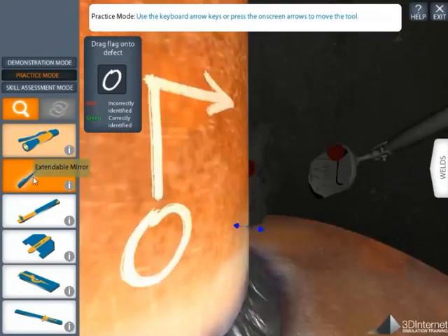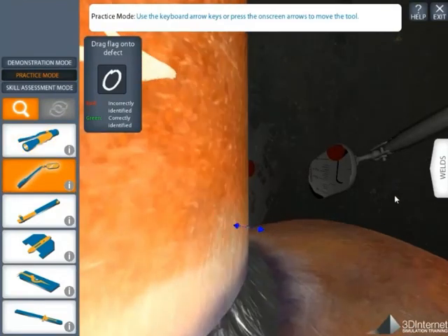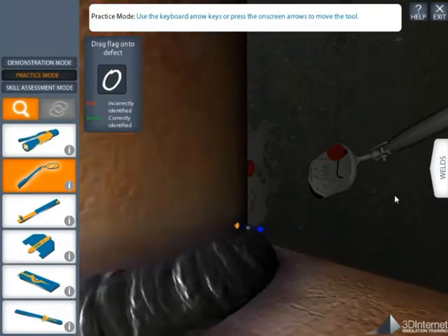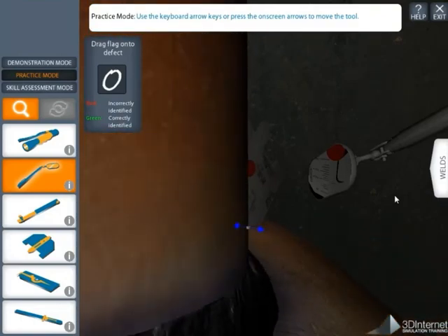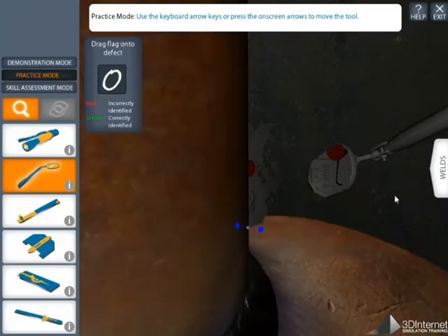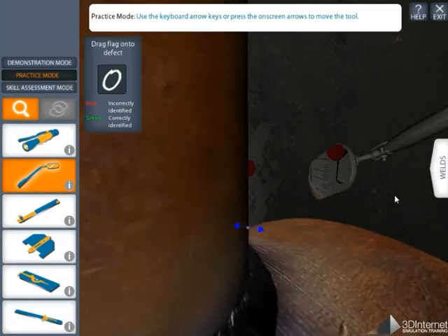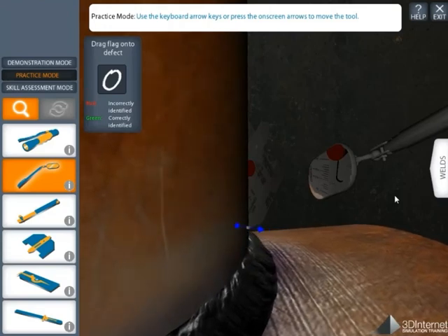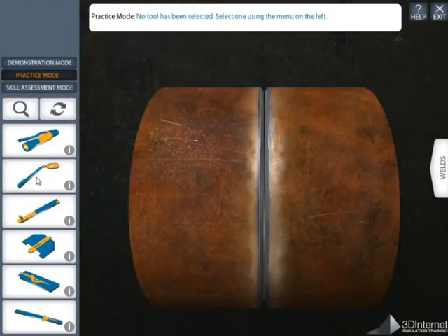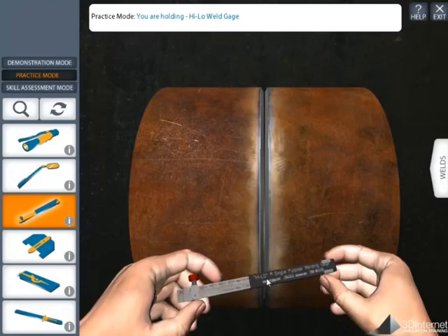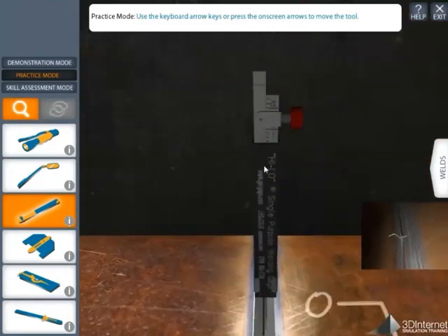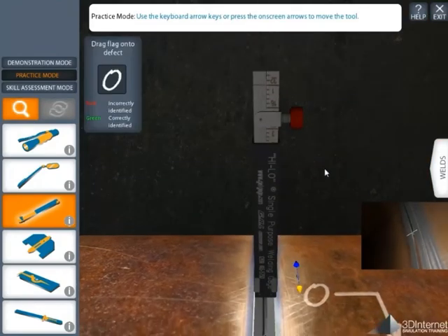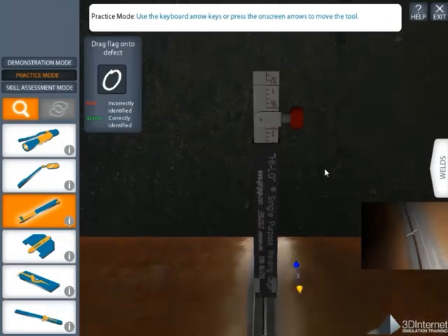Inspection mirror. The inspection mirror is used to view inaccessible areas. The inspection mirror has a 1-inch by 2-inch mirror. Its overall length is 8.5 inches. A handy pocket clip, an all-angle ball joint which holds the mirror head firmly at any angle, telescoping and pocket models. High-low single-purpose welding gauge. The high-low gauge is used to perform two high-low measurements, pipe alignment and internal misalignment on one end and the root weld space on the other end of the tool.